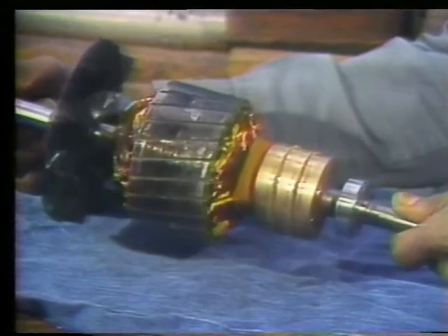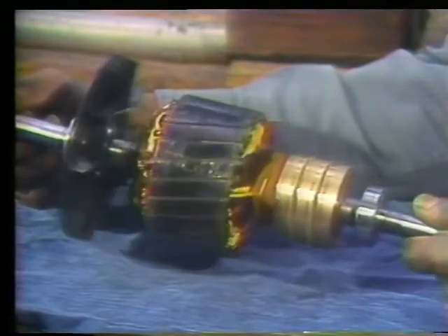Be careful when you check your readings in either of these tests. If you see there's a very low one, there may be a short in the circuit you're testing. To detect a short, first eliminate grounds and opens as possible causes of the motor's trouble. If there's no indication that a ground or an open exists in any part of the circuit, then suspect a short. If you suspect a short in the rotor coils, remove the rotor and visually examine it. Look for burn marks, which are a sign that a short has occurred.